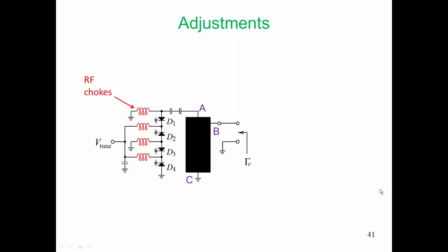First, we have our RF chokes and we have a DC block. The top two capacitors there provide a capacitance adjustment. Now we have two capacitors there. Those capacitors could have different values and give us a much wider range of adjustability. It just so happens in the final design here that they're both half a picofarad. But you could find in some designs maybe one could be 1 picofarad and one could be half a picofarad. And so we can achieve a much wider range of capacitance values and much finer adjustment as well.